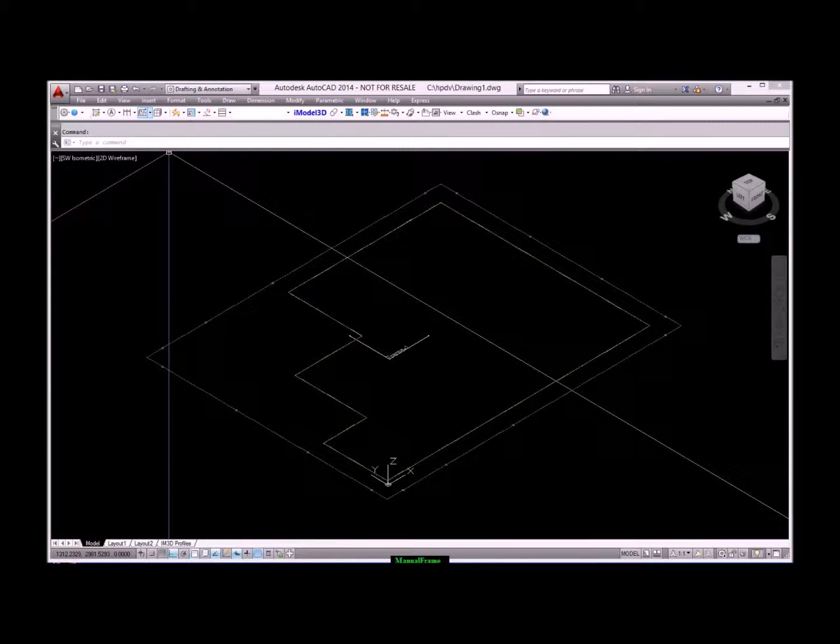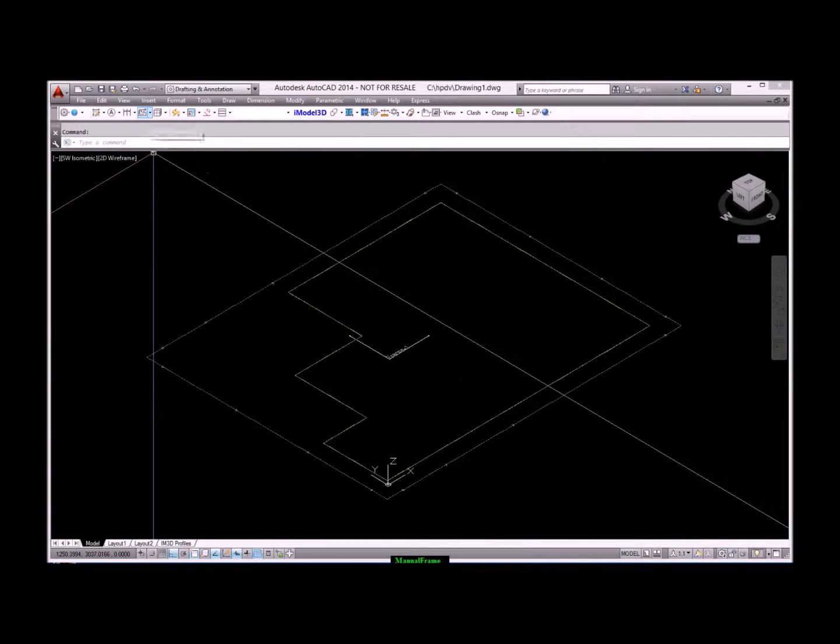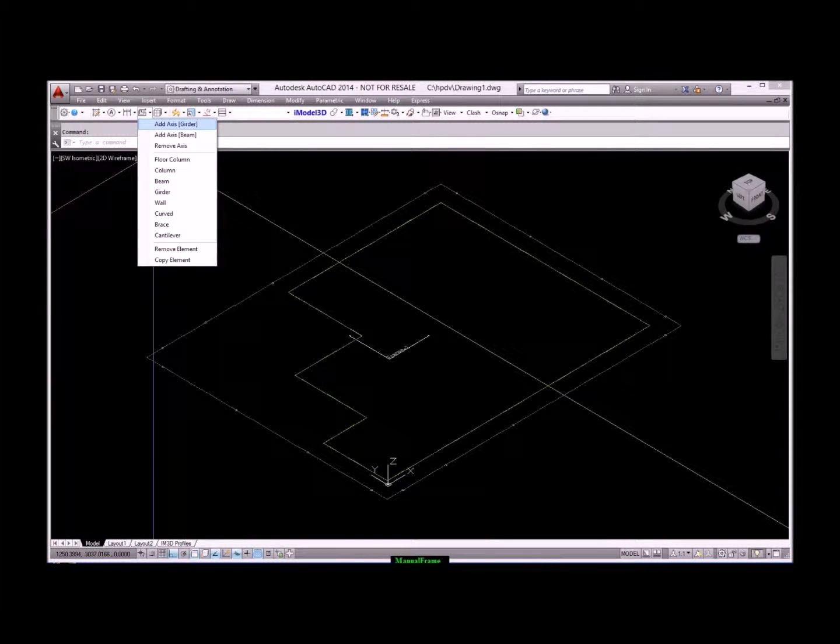Automatic space frame creation uses the building boundary and the floor axis together with the number of floors to generate it. In this method, all floors are assumed to be typical. Manual space frame creation is a step-by-step method to model each frame element separately. This method is more generic and gives the designer more flexibility while it takes longer. The menu shown above has several commands that allow you to model a manual space frame.